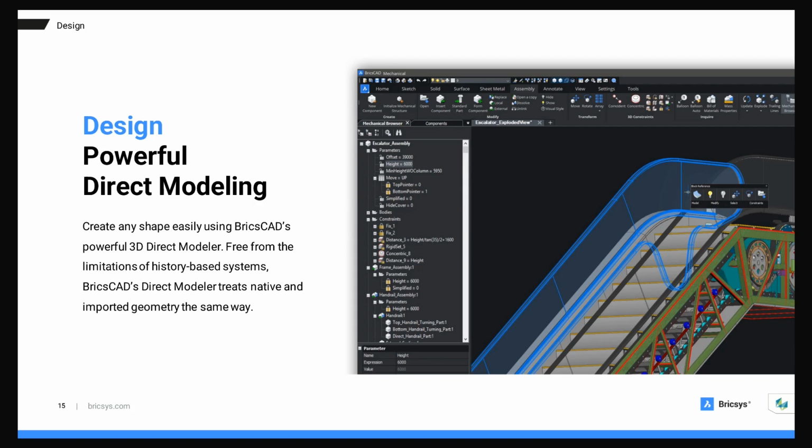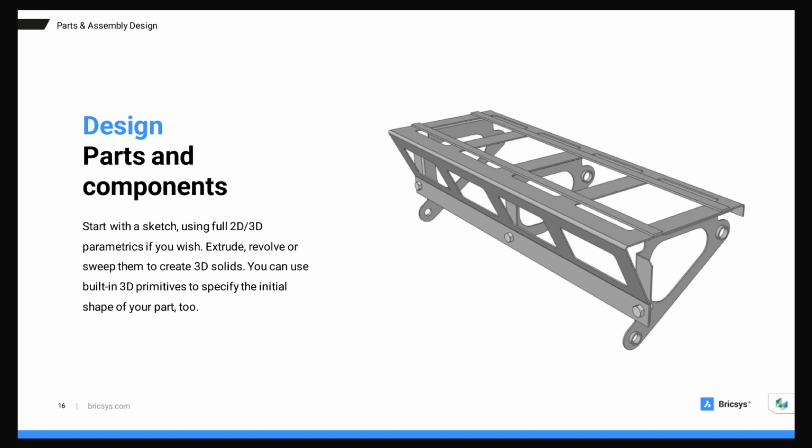And of course, another sweet spot of mine is sheet metal. I started off as a sheet metal fabricator using AutoCAD. And I remember those days when I would have to work out the K factors, the bend allowance on a 2mm gauge. And I couldn't grasp the fact that when something gets bent, and you've got a couple of folds in there, when I need to cut that out on a plasma or a laser or a water jet, if we're ever so lucky, the material is going to stretch, it's going to grow and decrease in certain areas. You're going to take this into effect, and doing this in 2D was a nightmare.